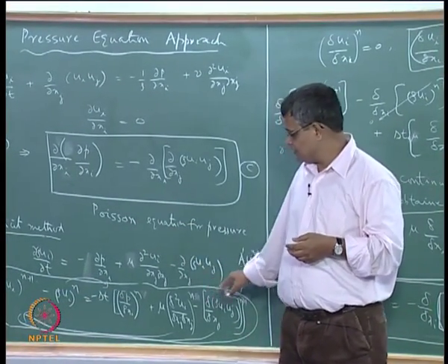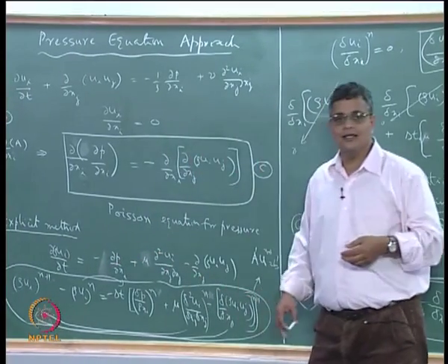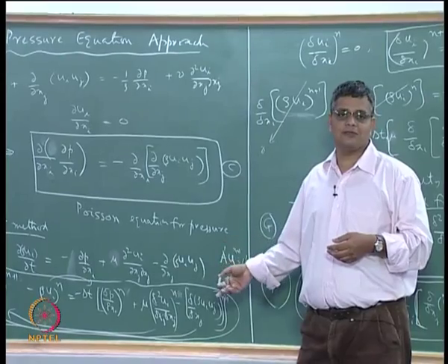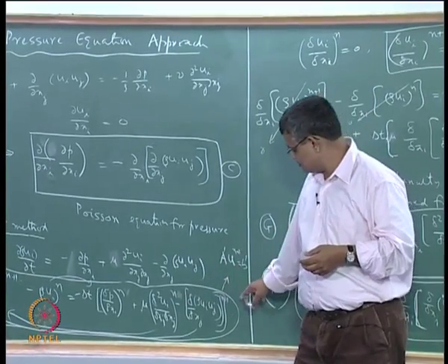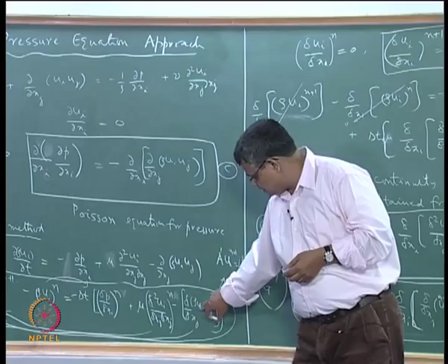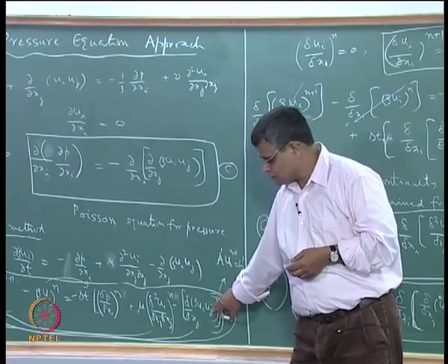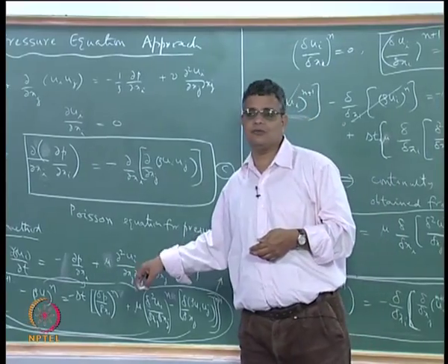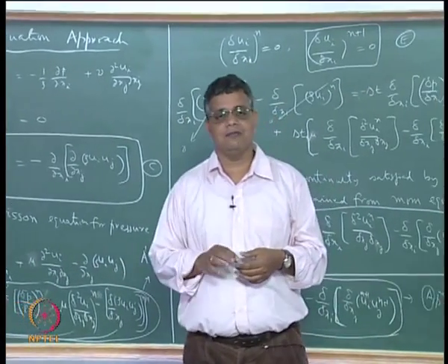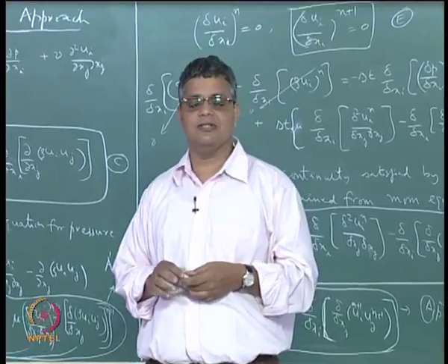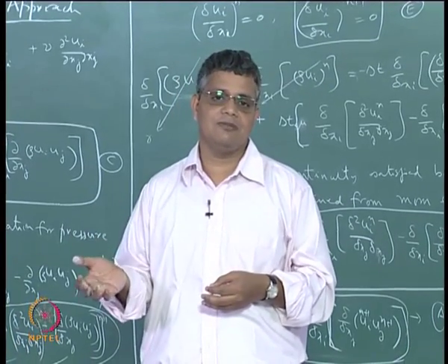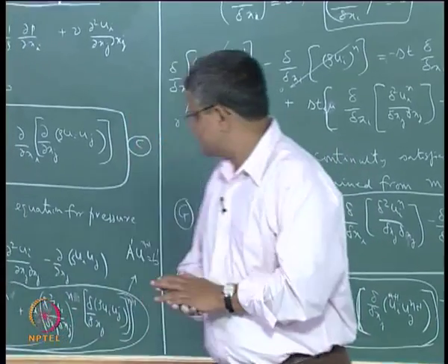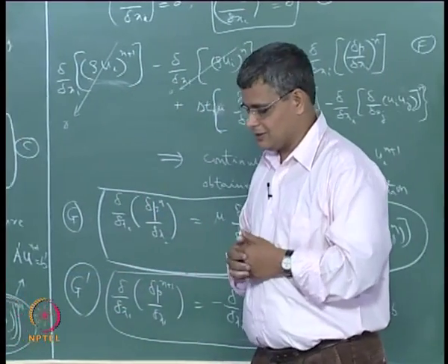In the case of an implicit method, because we are solving this with constant and specified coefficients, there should not be any time step limitation, but because of ui uj kind of terms where you need to know the velocities of the other components in the solution of x momentum or y momentum, there that brings in some possibility of instability. So we can use large time step but not very large time steps. So this method is possible and it is quite used.